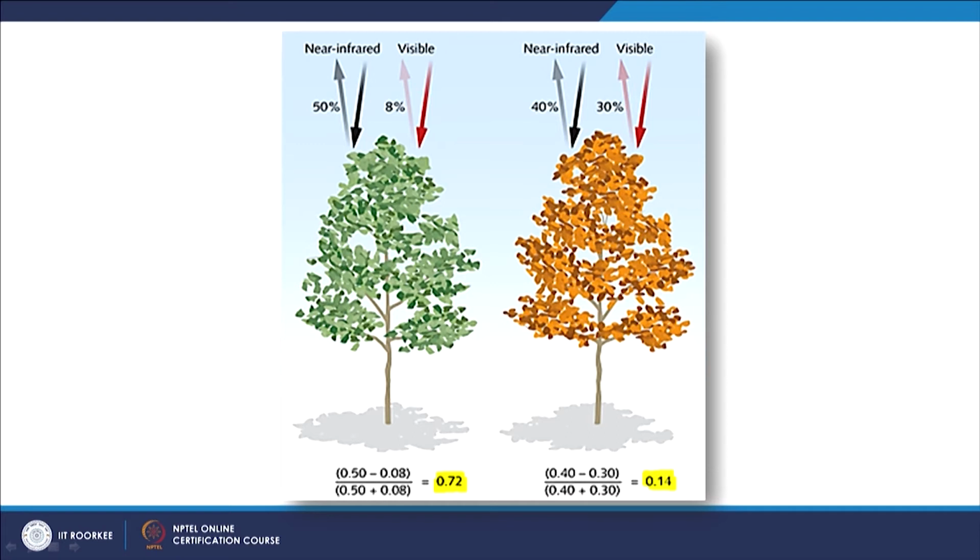So, you can understand very easily that a vegetation which is healthy, having high chlorophyll content, will have a high NDVI value, whereas a vegetation which is under stress or drying up will have relatively very less chlorophyll content, as in this example, and of course less NDVI value. So, that is the advantage. Instead of a simple band ratio, if we apply the NDVI, the normalized difference, because we normalize by multiplying some factor, or in an 8-bit scenario maybe 255, we get an index, and that tells us the health of a vegetation.